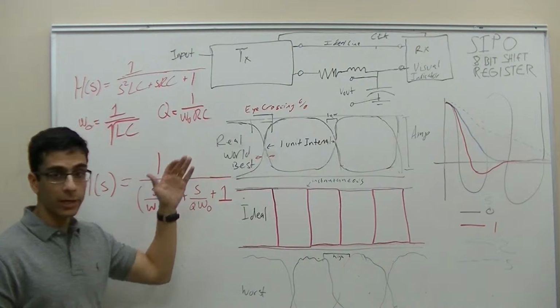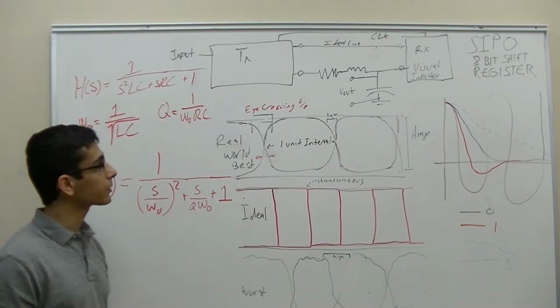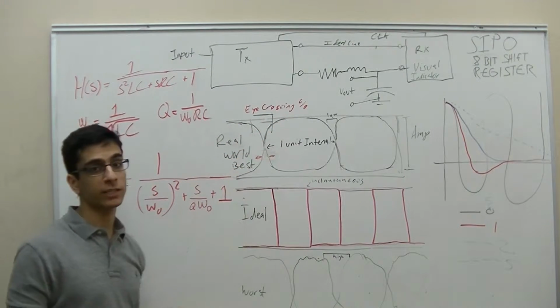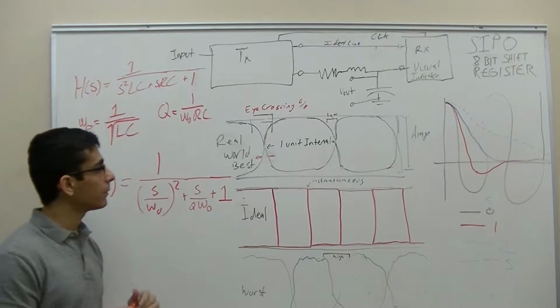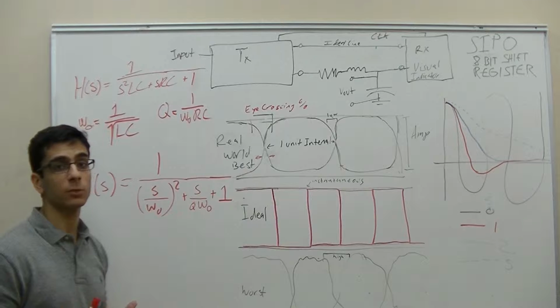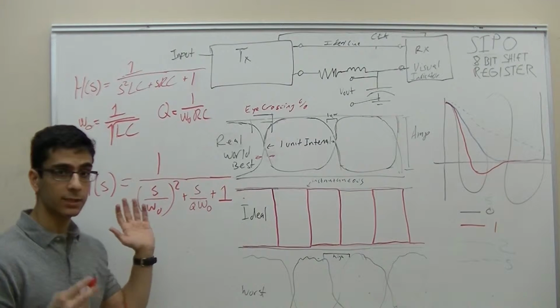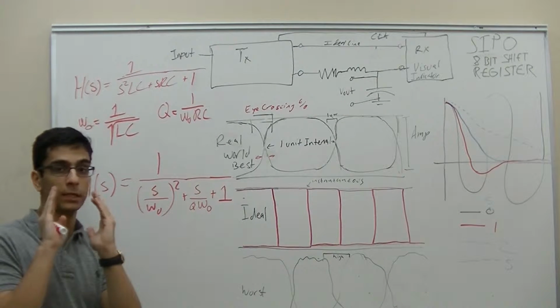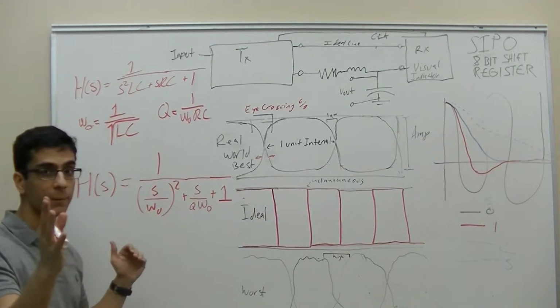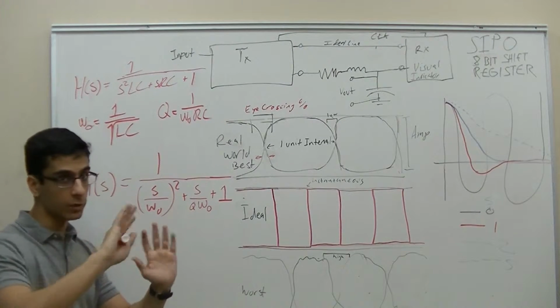So now to get to how we're going to measure and analyze our signals. We're going to be measuring across the capacitor using an oscilloscope in persistence mode. When an oscilloscope is in persistence mode, it basically eliminates time, and it doesn't measure in any intervals. It measures across all time, and it keeps it on the oscope, and it never erases.